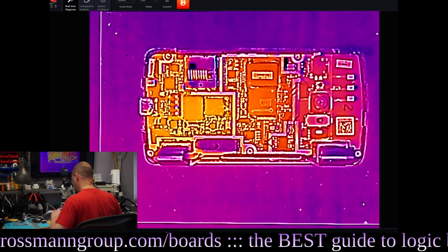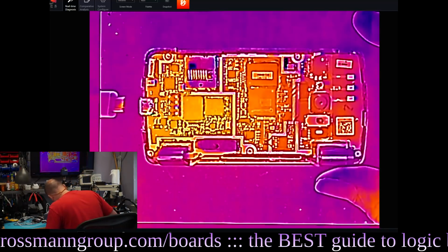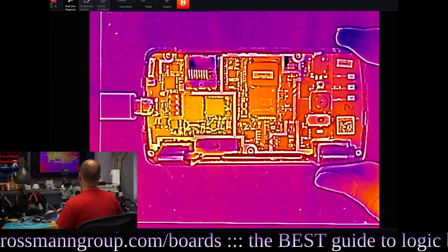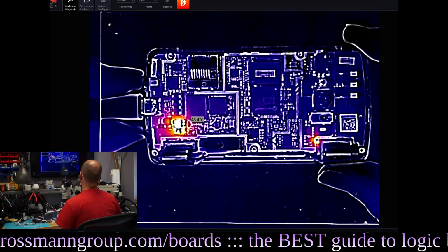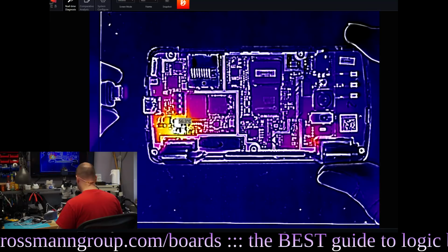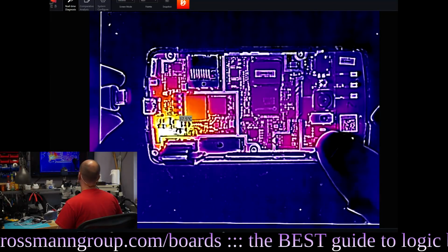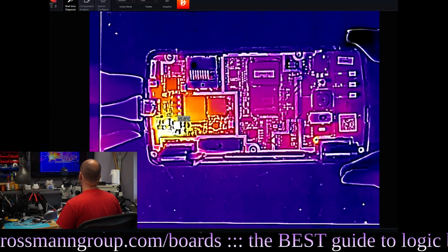So this, which board is this? Is this the donor one? This is the data recovery board. Okay, so let's see what it is we need to do here. So we plug that data recovery board in. Look at that. We got 2 shorts on the board. Wait, do you see the temperature on that? Plug that back in. Look at what the temperature says on the screen.